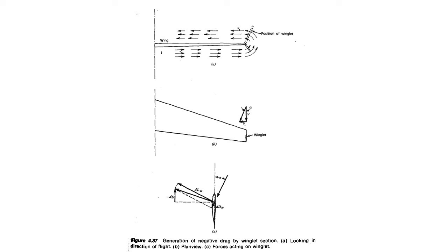This net force can be generated by a winglet above or below the wing. If the vertical surface is extending downwards, the resultant lifting vector of the winglet points outboard due to the local induced velocity, but it's still ultimately tilted forwards. Naturally, to maximize this effect, we should be using cambered airfoils that will be effectively lifting inwards towards the wing root. Some people just assume that a symmetric airfoil cross-section for the winglet is okay, but this is just lazy, and you're leaving gains on the table to save a few minutes of preliminary analysis and calculation.